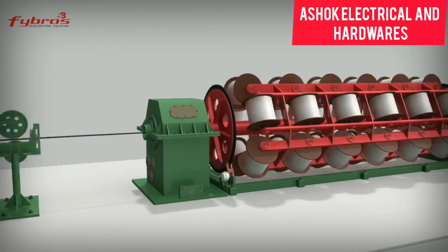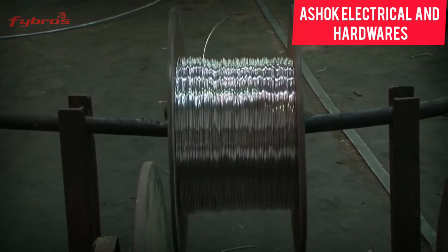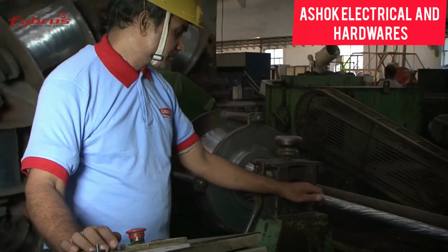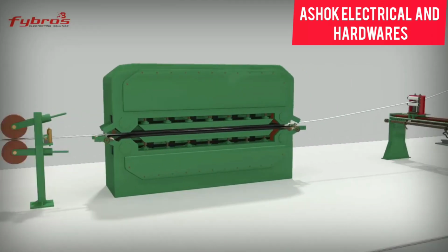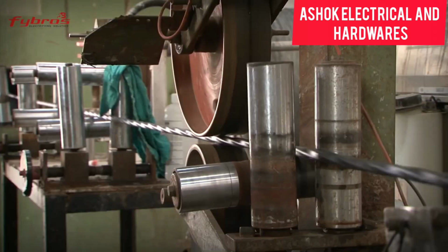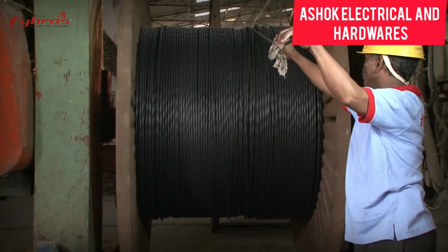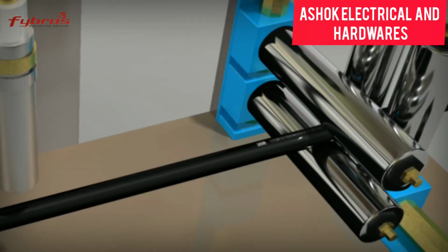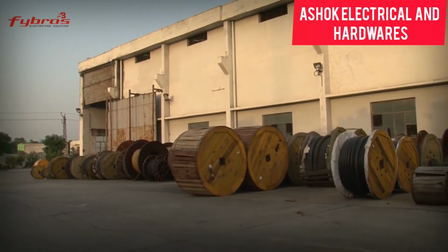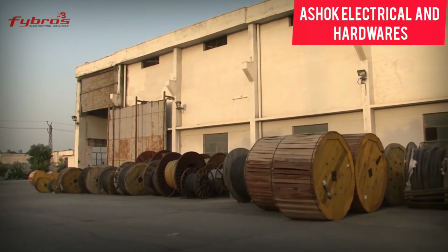Armoring is done with a 48 bobbins machine using galvanized steel or aluminium strip wire. Next, extrusion of PVC outer sheath is done. Branding and measurement mark along with embossing of brand name is done to standardize the cables. Finally, all cables are rewound on wooden drums. Cables are tested before being sealed and packed for dispatch.